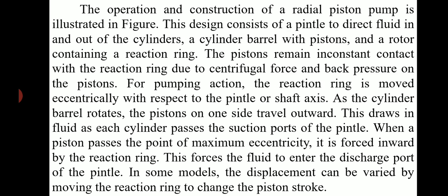This design consists of a pintle to direct fluid in and out of the cylinders, a cylinder barrel with pistons, and a rotor containing a reaction ring. The pistons remain in constant contact with the reaction ring due to centrifugal force and back pressure on the pistons.